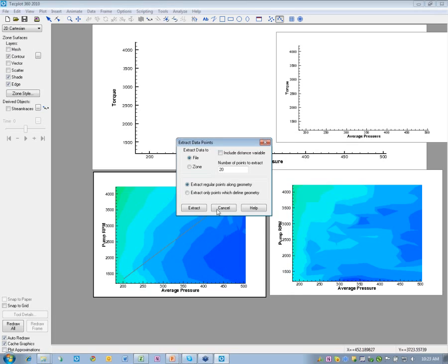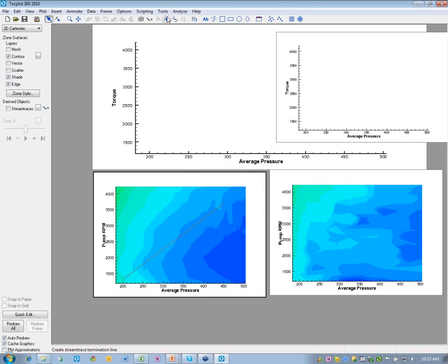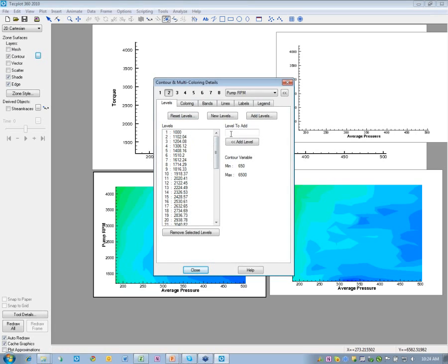Right. So how are you able to add contour lines using the mouse? There is an option in Tecplot called add contour levels. If you select that mouse functionality, then you can just come in and add them interactively. Of course, you could also do that the old-fashioned way, which is to add a level. Let's say I wanted 340, I can add that level as well.